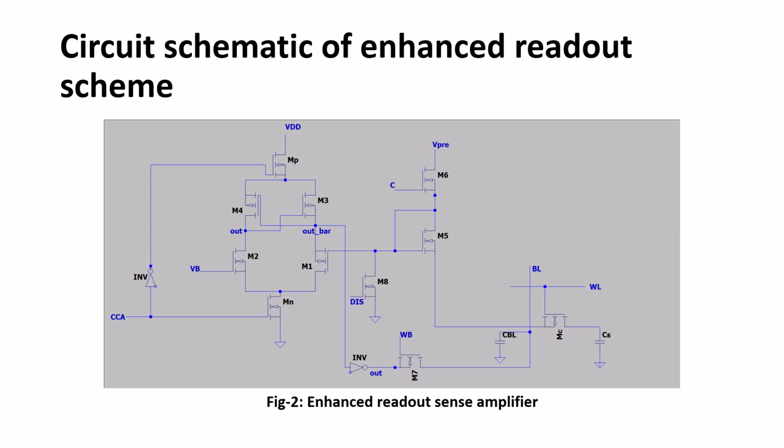As this voltage is pulled to VDD, this transistor turns off respectively. Now, compared with the conventional DRAM cell, there is a difference in this readout scheme. We have seen that in a conventional DRAM cell, the storage node capacitance, for example having some logic 1, requires some time. I mean, some sensing voltage delta V has to be developed across this CBL, V plus delta V. So in order to create some delta V, there is some time required in the case of the conventional DRAM cell.